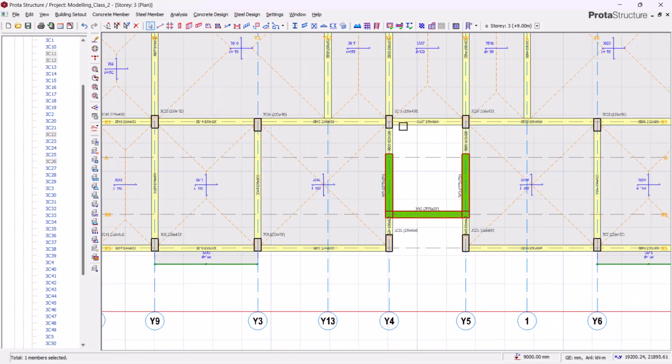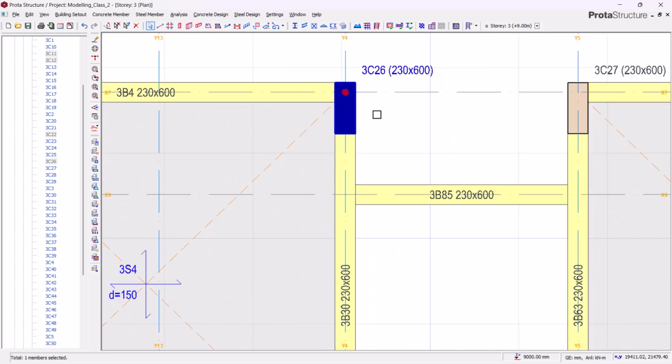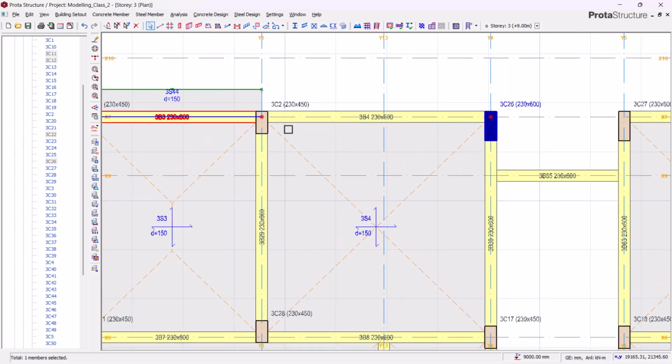Okay, so every other thing can align from this face coming to this other part. That is why we are maintaining these very column sizes from the ground floor and possibly to the apex. So that's the reason behind keeping this column here, and not necessarily because it is carrying more load than the column at this very point.